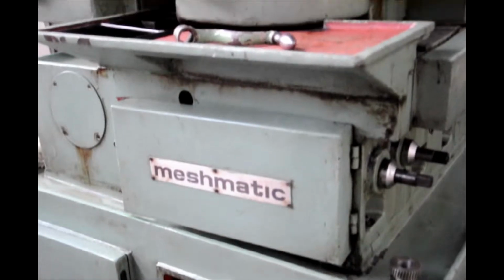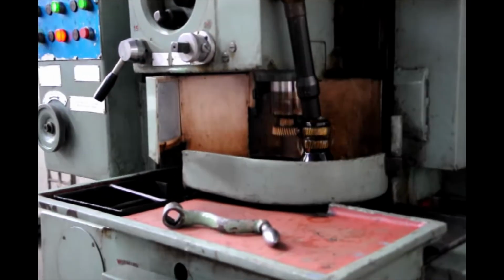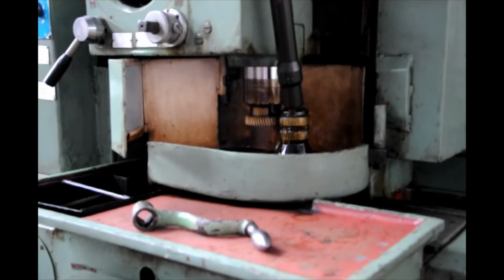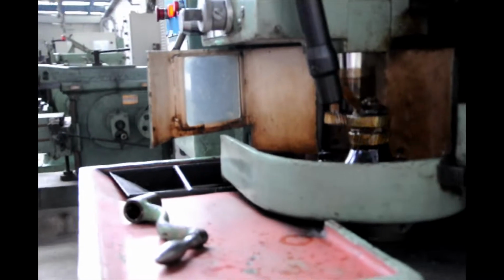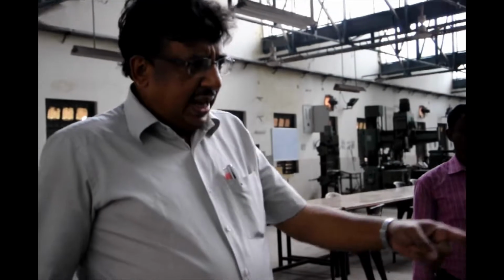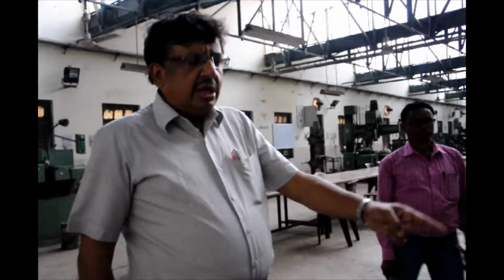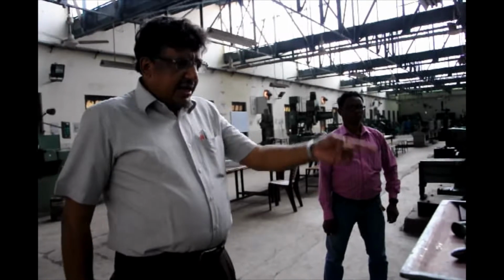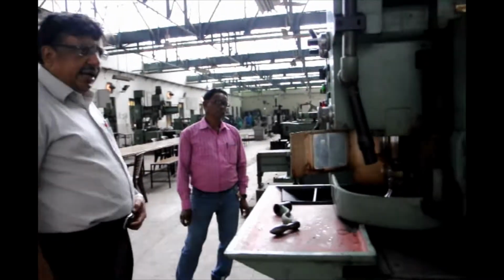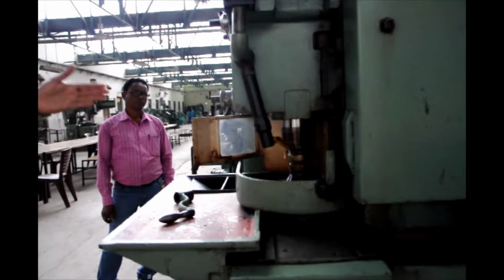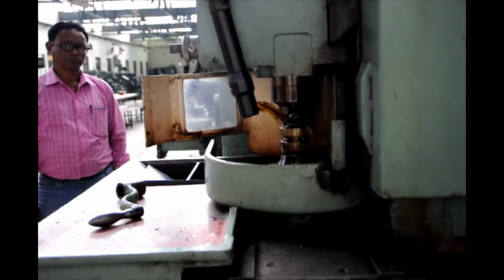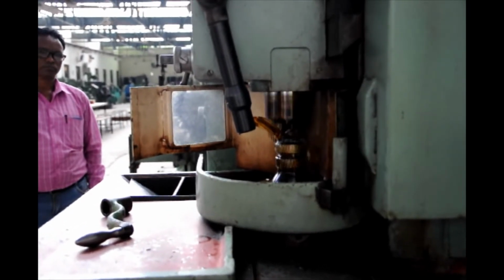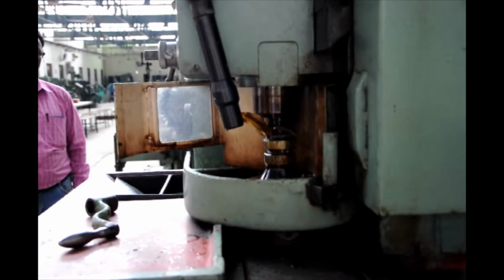The most important parameter of a gear is gear module. Gear module will determine the mating criteria with the other type of gears. So gear module for the spur case is PCD divided by number of teeth. So according to that, all those things are set, and for the different modules, different cutters will be associated with this cutting. And for the different helix angles also, different cutters will be there. So that oblique part associated with that has to be fixed in the cutter. So once the cutter is there and decided, one can go for mass production.